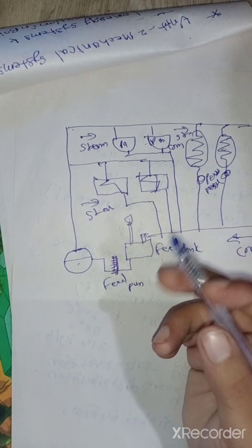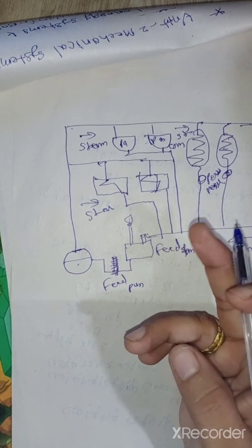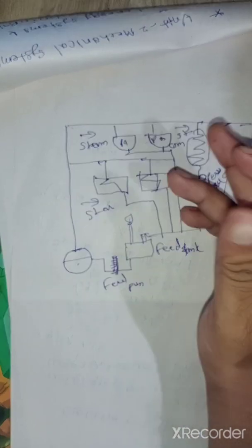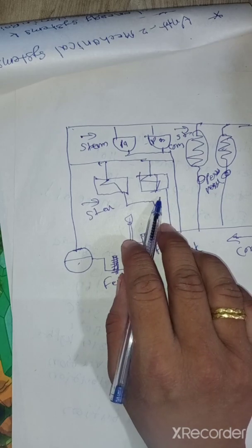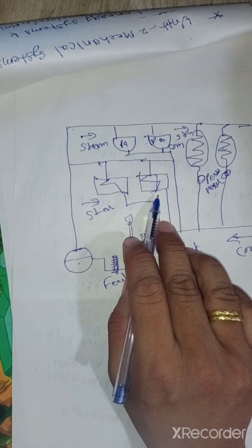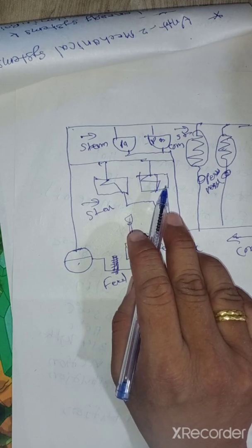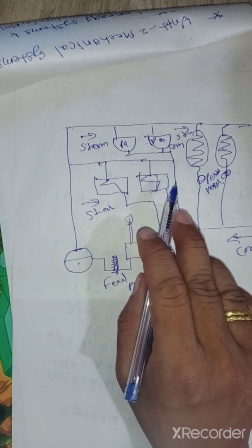The steam generated in the boiler must be conveyed through pipe work to the point where its heat energy is required. Initially there will be one or more main pipes, or steam mains, which carry steam from the boiler in the general direction of the steam-using plant.